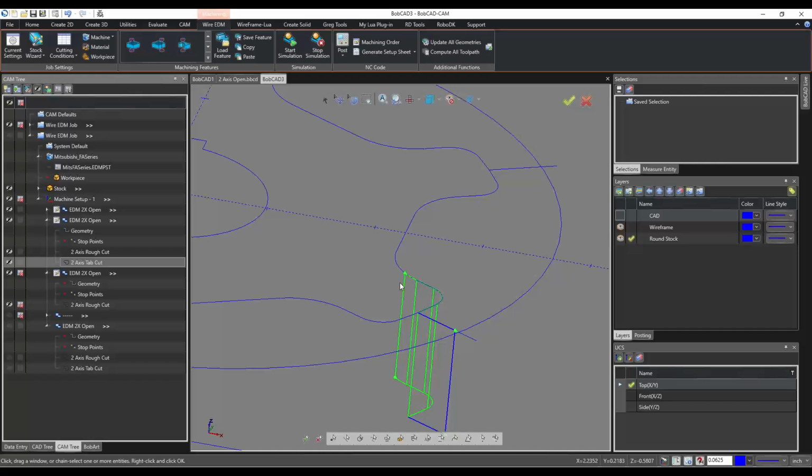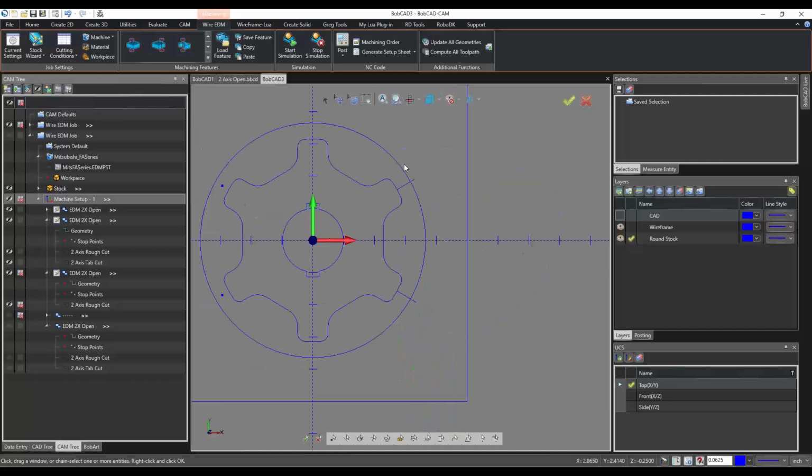The difference between those is that this is open geometry. In other words, the geometry that I've selected here is open-ended. It doesn't connect together. It just starts over here and ends over here. If I wanted to use inside or outside, that would be like selecting this entire piece here, because this is all one connected chain, with no point that's disconnected. That's when you would use the other two. So hopefully that clears that up a little bit.